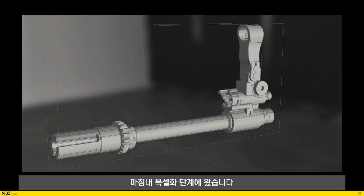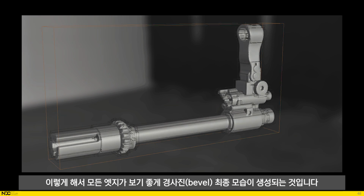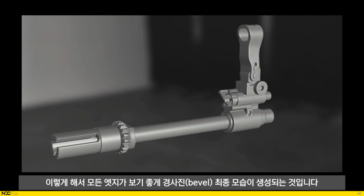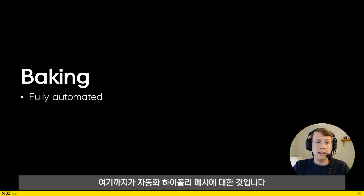We're finally at the voxelization step. When everything has been converted into voxels, smoothing operations are applied to the volume before it converts back into polygons. This is what creates that final look of all edges being nicely beveled. Since the resulting geometry can easily be tens of millions of polygons, a mesh reduction is being run in order to speed up the loading of the mesh for the baking process. And that's it for the automatic high poly meshes.